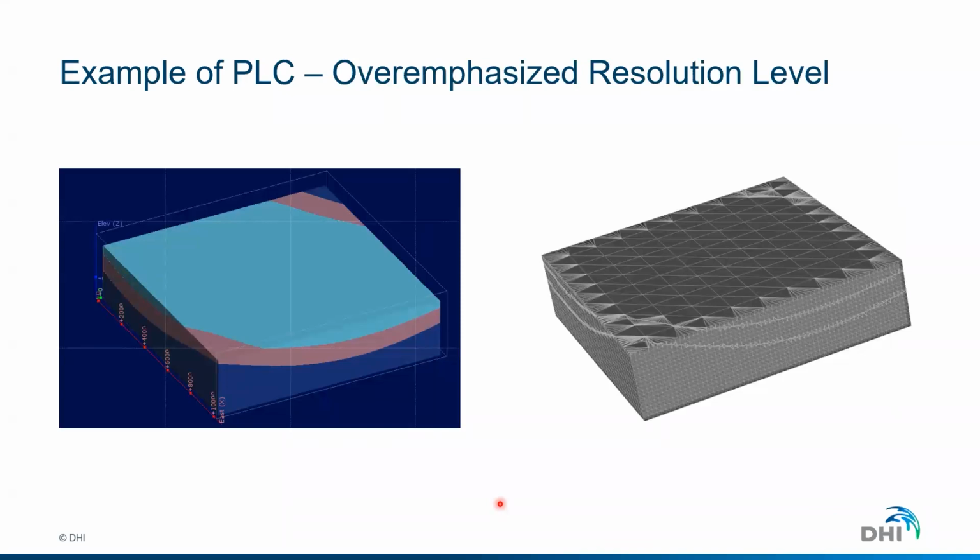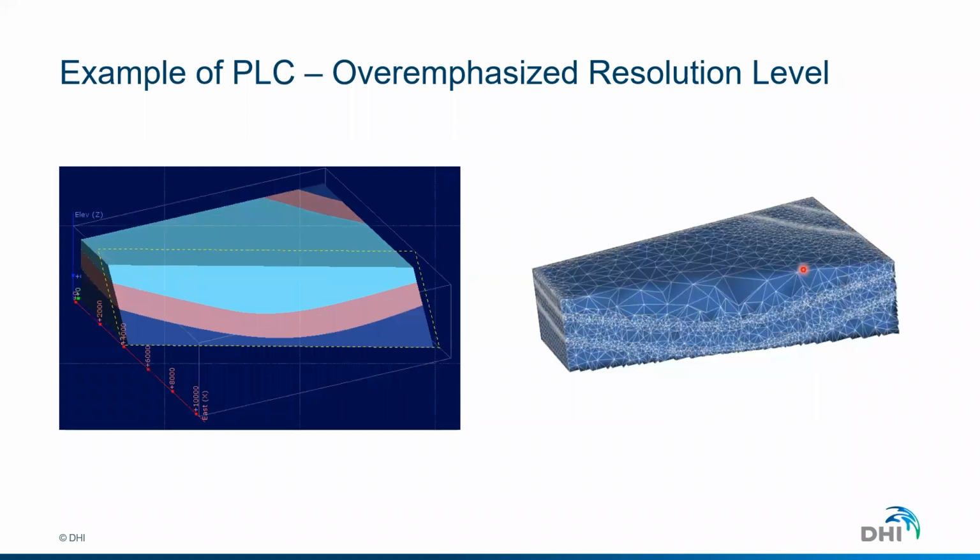That's another example. Here is a simple 3D layer. One typical situation which we observe quite a lot is that the input triangulation coming from the geological software sometimes overemphasizes detail unnecessarily. You see all these triangles. They are going to perturb my final finite element model in FEFLOW. This is something that you need to take care of in the software outside, or use our new tools today.